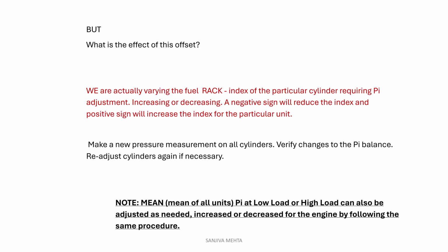Video 3, module 6. Okay, we are adjusting PI. But what are we doing to the engine? What is happening to PI is actually the power curve being elongated. You have seen the power card, no? Start from here, scavenge, goes high in the compression cycle. You are actually making it fatter or thinner. So that is the average pressure.